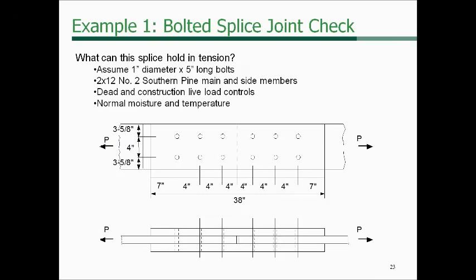This part of the example can also be trial and error. Because if you get your edge distance or end distances or spacings too small, you're going to get some reductions in some cases.